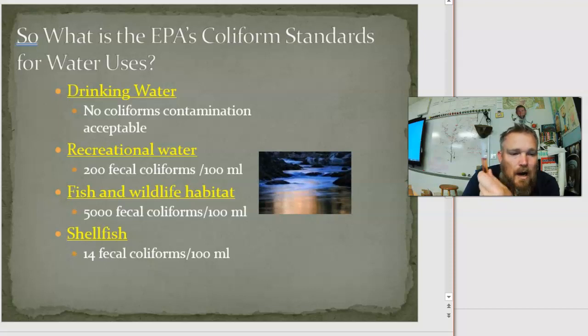So why did we close down on Thursday and then we couldn't find out until Saturday? Because they did this very test on the system. They basically take these, put a milliliter of water in there, let them sit for 24 hours, check it, and then if it's not yellow, that's a good sign, but you have to wait another 24 hours. If it's not yellow after 24 more hours, then we can say it's safe to drink. So we have that ongoing right now.